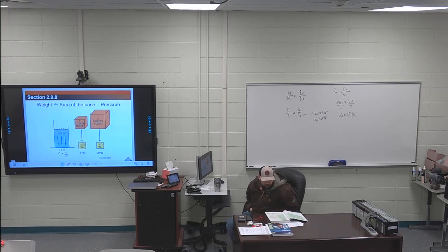On the right hand side of the page, you see gauge pressure highlighted in blue at the end of the paragraph. Gauge pressure is measured and expressed as pounds per square inch gauge, or PSIG, or kilopascals gauge, and considers the presence of atmospheric pressure. For gauge pressure, the starting point of 0 PSIG actually begins at the atmospheric pressure. So what do we say atmospheric pressure is at sea level? 14.7. We are at sea level.